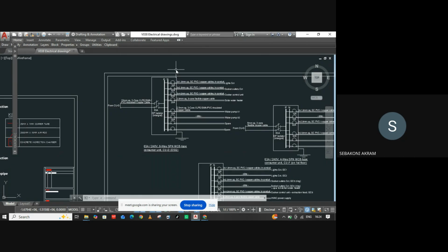We select the circuit breaker that is bigger than the what? At a higher capacity than your calculated load. Then it's from there that we select the cable size from our British standard, BS 7671. Are we together? Yeah, you have to familiarize yourself with those tables.